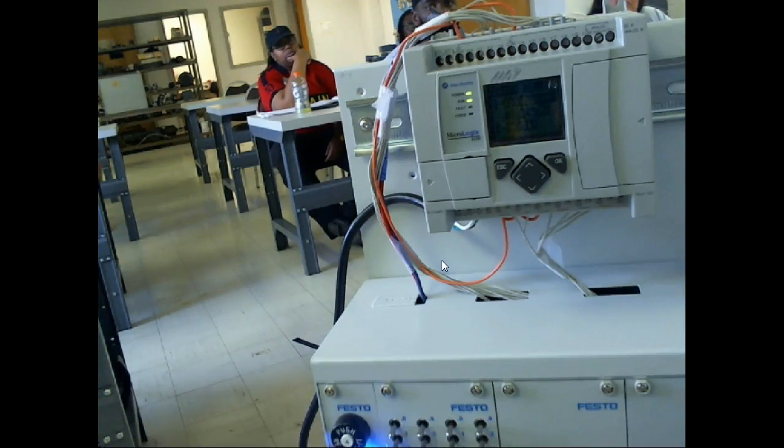Once you understand one, so I can't find the wiring diagram for the 1200 PLCs. I've looked all over for that so I could show you, but I don't need it, right? Understand? Because they do what? The same. Except on the Siemens PLCs, the minus they label as M, and the positive they label as L, plus L. That's the only difference. So the inputs have an M, and you can either use the internal power supply, right, or you can use a what? External power supply.